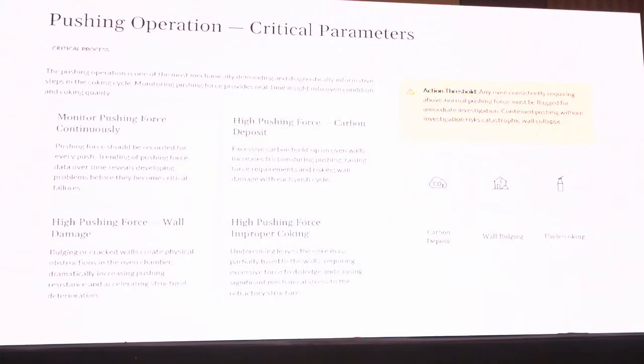Pushing operation is a very critical parameter. Monitoring pushing force provides real-time insight into the oven conditions and coke quality. We should always monitor pushing force to avoid oven failure. High pushing resistance is due to the carbon deposits which affect the walls of the ovens.